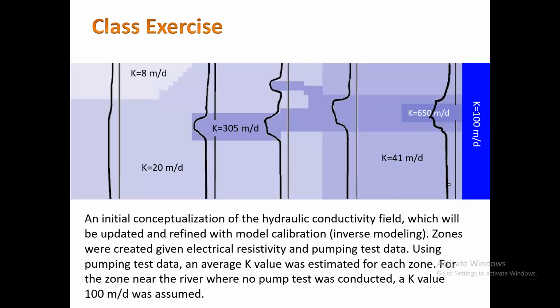Okay, I have this equation. In this equation, I define my hydraulic conductivity field. This is what I did here. Then I have to define my boundary conditions. So I have a recharge, a pumping well, a river, and then I have all these no flow boundaries. MODFLOW, if you didn't define it, would consider it a no flow boundary.